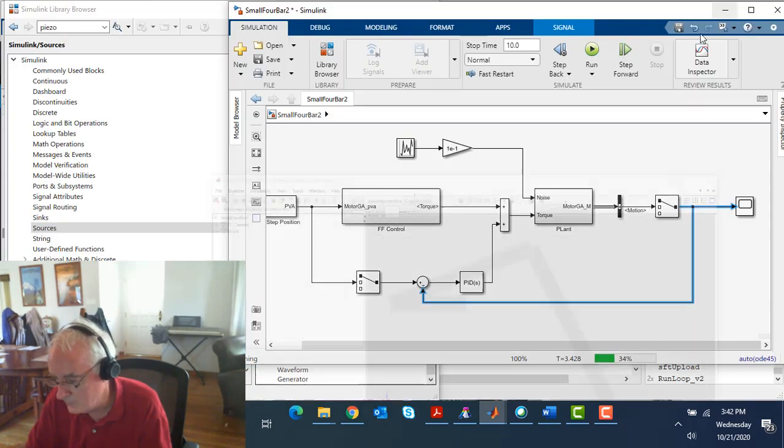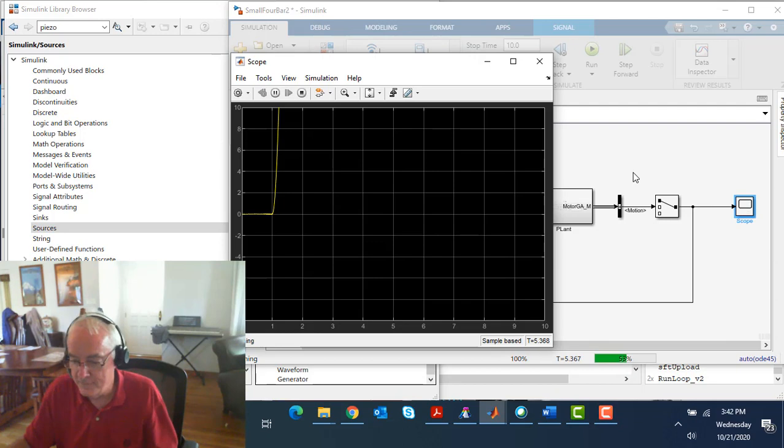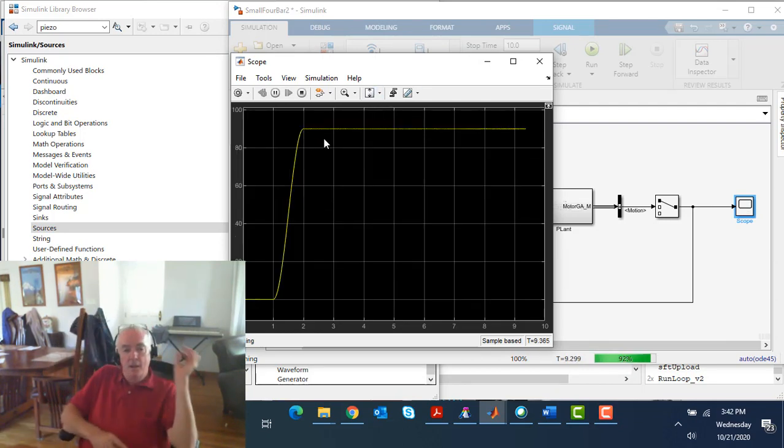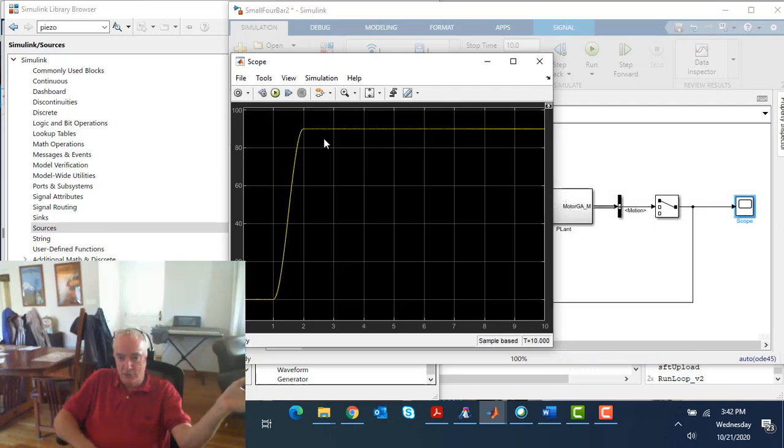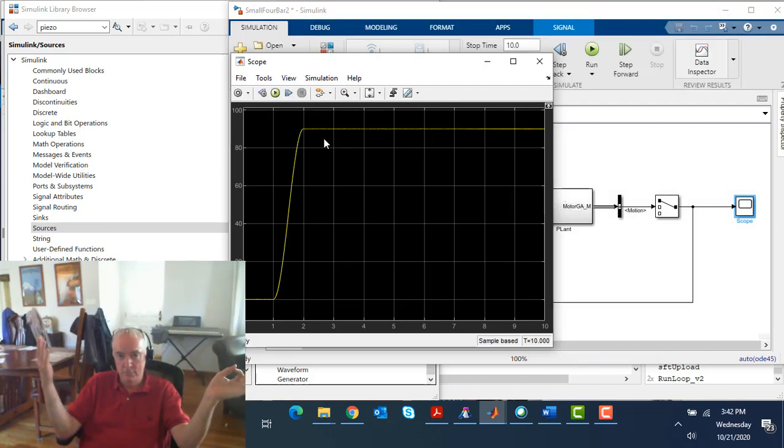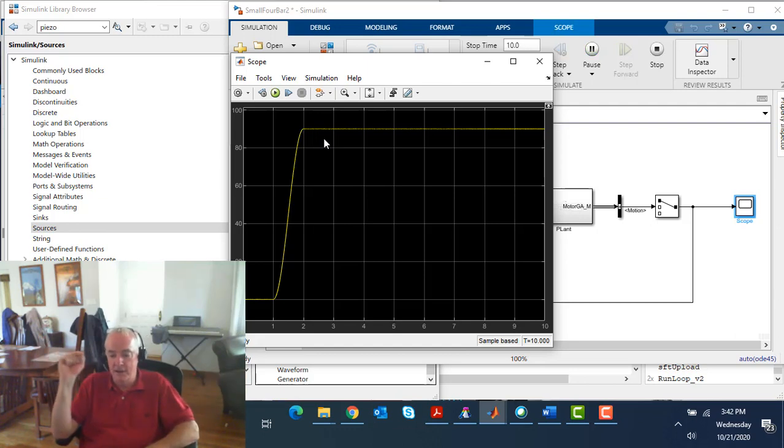All right, it works beautifully. Yeah, and we know that because we're not seeing any differentiation between the movement of the 4 bar used to calculate the ideal torque and the one that's responding to that torque, right? But now has a little bit of feedback and we're seeing perfect movement. So anyways, I just want to state that feed forward is awesome and never, ever, well, I'm going to be a little careful on that. Most often, you do not want to use feed forward all by itself, right?